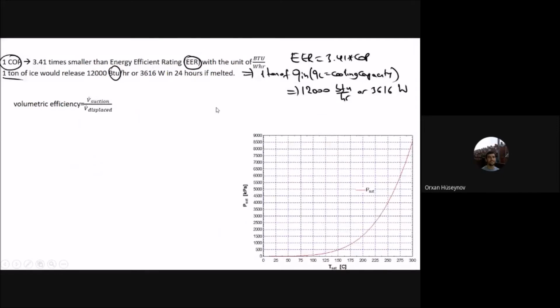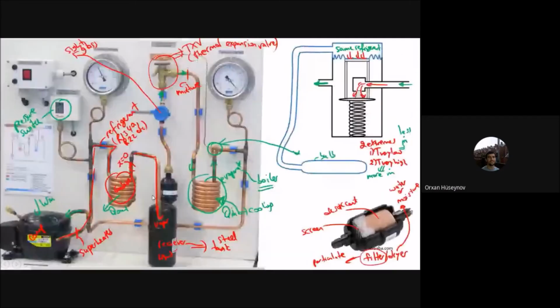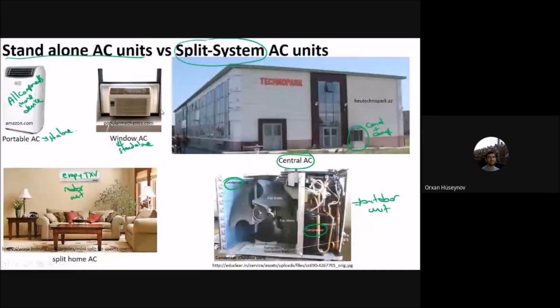One more thing I should tell you: this evaporator part takes Q in, therefore it cools. For refrigeration, we take this part. But a heat pump is when you are heating the system. If it is refrigeration, your aim is Q in or QL. If it is a heat pump, these are the same components, but our aim is Q out or QH.